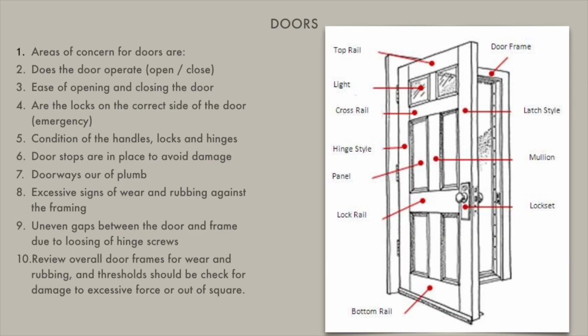Areas of concern for doors are: Does the door operate? Ease of opening and closing the door. Are the locks on the correct side of the door? The condition of the handles, locks, and hinges. Are door stops in place to avoid damage? Doorways out of plumb.